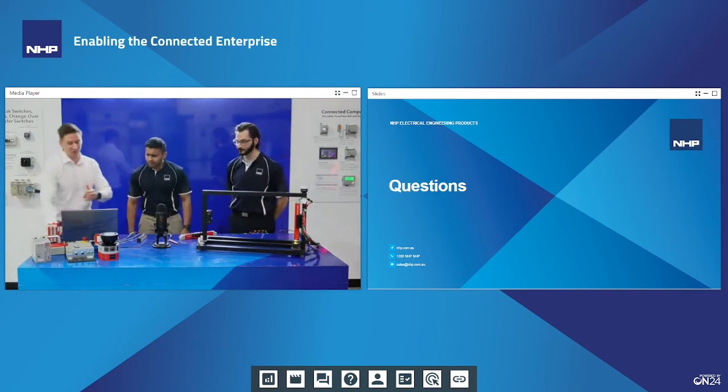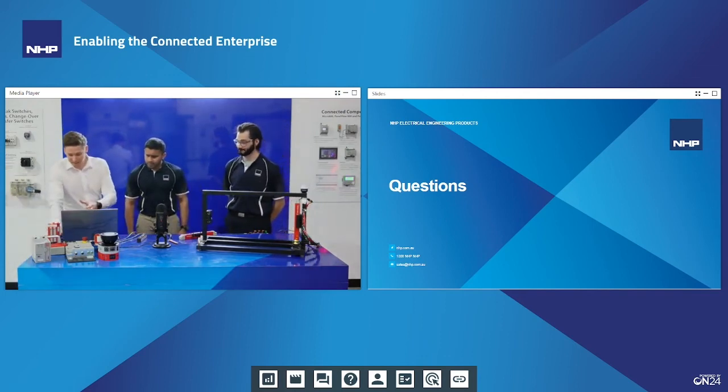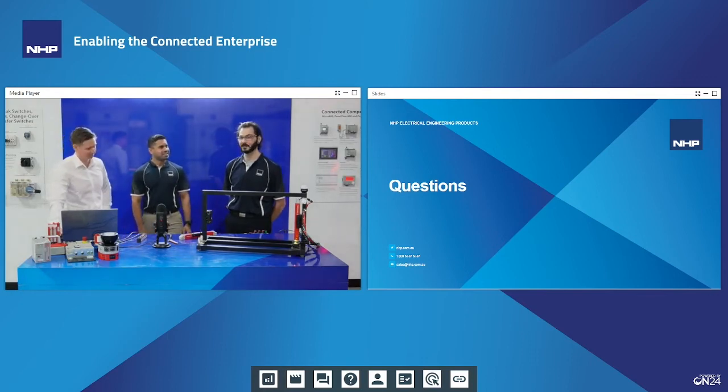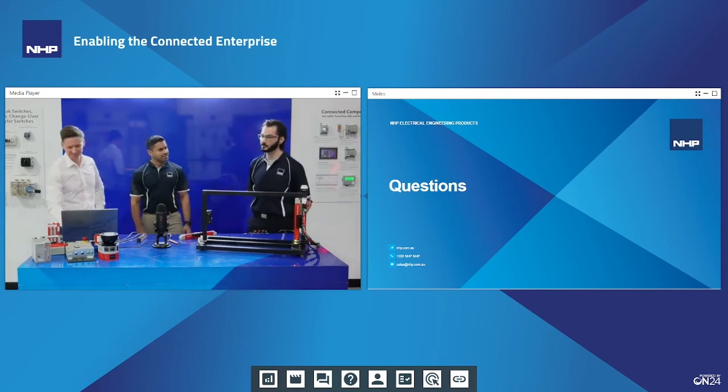So on the back of that, Michael's actually asked, can we confirm if VSD drives can meet a Cat 4 or is it a Cat 3 safety only rating? Depends on the drive. Can I leave it at that? Yeah. Complex. Depends. A single device is generally, you can't assign a safety category to it. It's all dependent on the architecture.